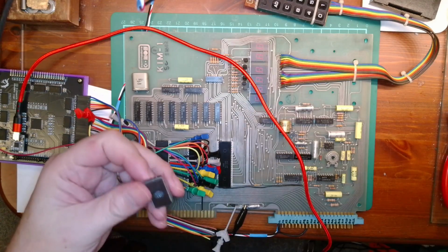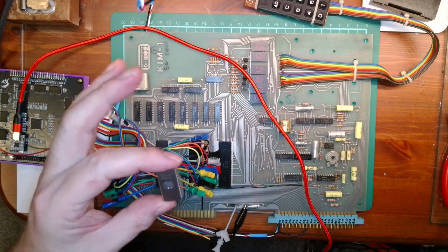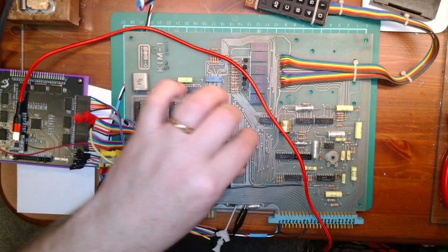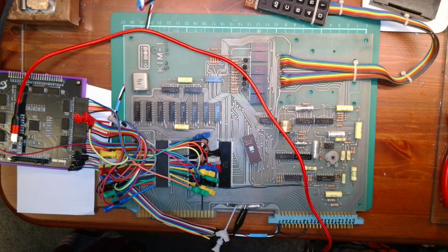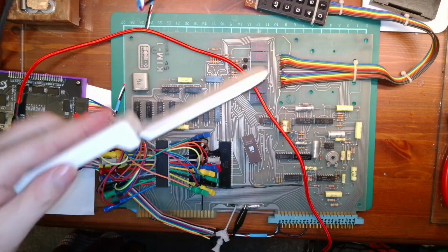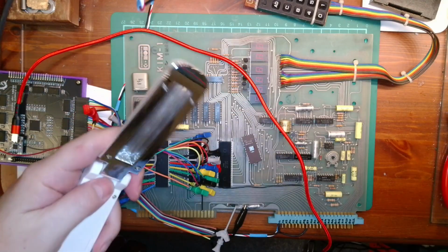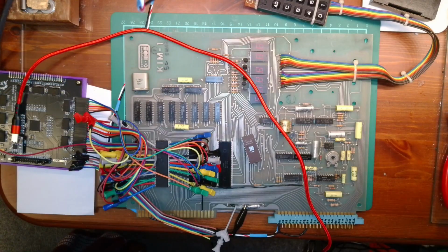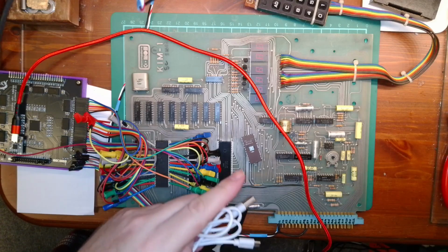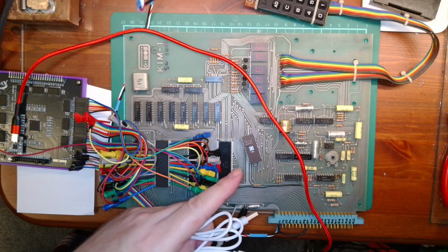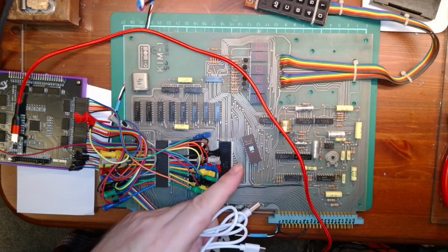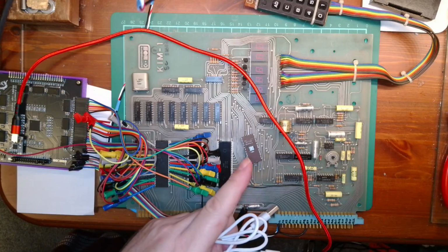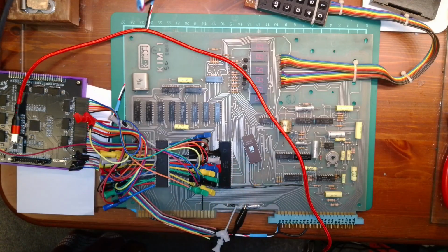Here's the actual ROM chip I should program. It's got something else on at the moment, so it needs erasing. And I found online this little device. It's meant to be a sterilising UV device. It plugs into a USB port. Just plug it in with a lead, and it's very good at erasing these. It takes 5 minutes, if that. I generally do it for about 10 minutes just to make sure, and then I'll reprogram that with a bit of code, and we go off and test some RAM and ROM.